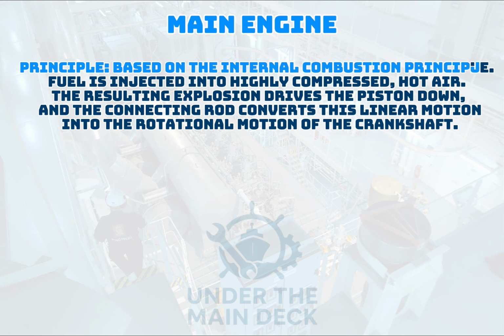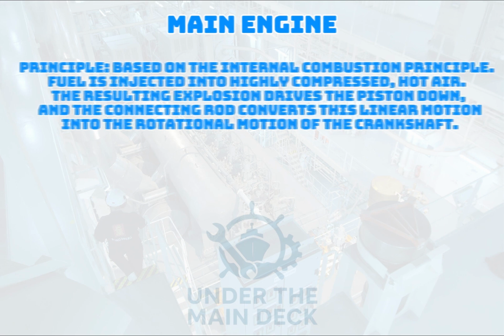Principle: based on the internal combustion principle, fuel is injected into highly compressed, hot air. The resulting explosion drives the piston down, and the connecting rod converts this linear motion into the rotational motion of the crankshaft.